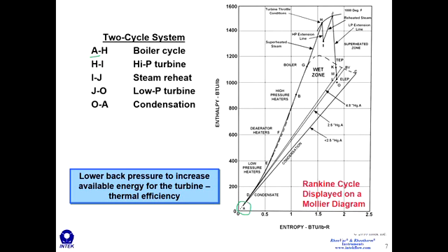This is the point at which the water in the steam cycle is at its lowest energy point. This is where the water is at the bottom of the condenser. It's at maybe 90 degrees Fahrenheit, and the enthalpy is around 70 BTUs per pound.